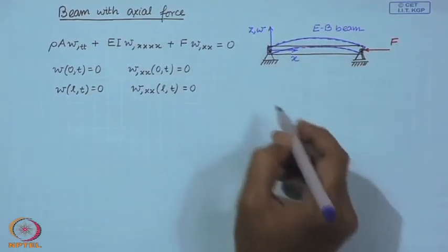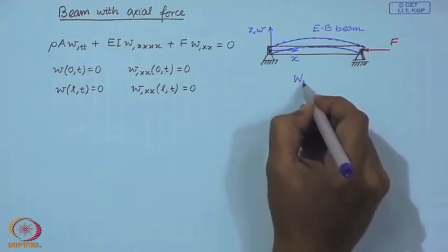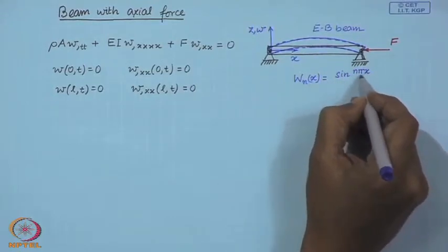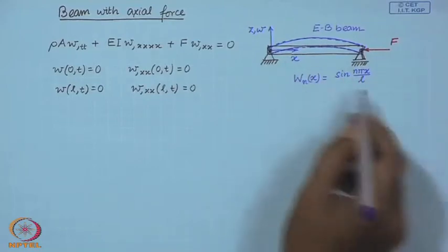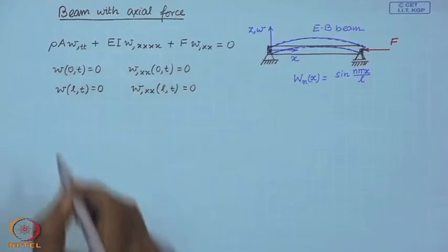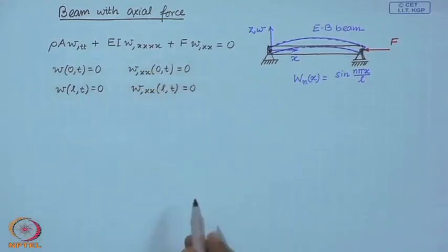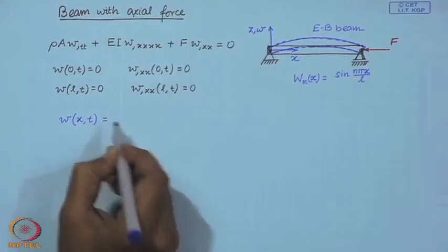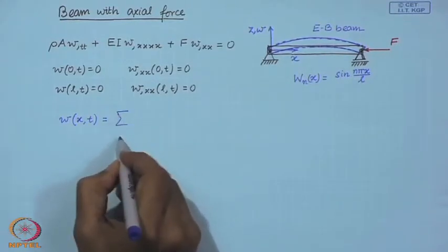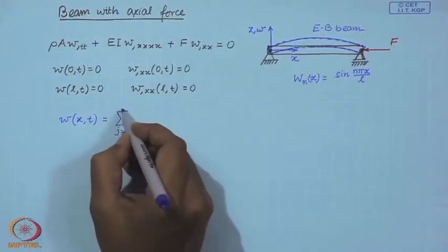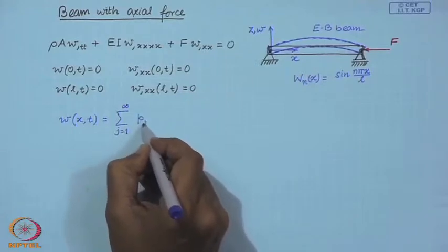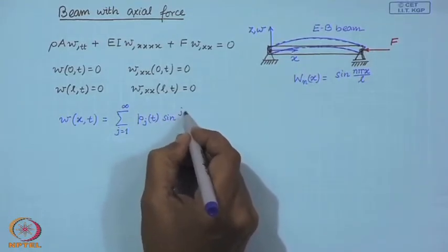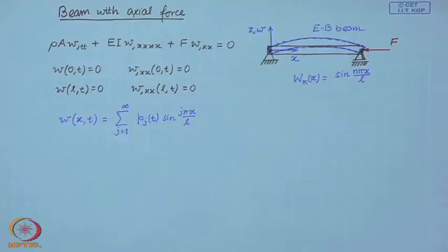We know that the eigenfunctions of a simply supported beam are given by sin n pi x over L. So, the solution of this dynamics with axial force, let us construct that solution as an expansion in this form.